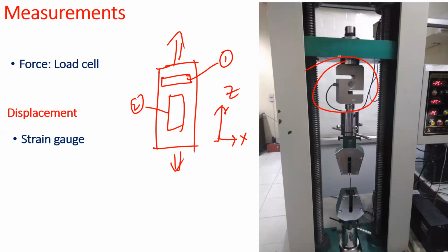So using strain gauges, one can measure the strains along the longitudinal as well as the transverse directions. However, the flip side to strain gauge measurements is that one has to always stick the strain gauge to the sample. It is a contact based measurement. It is still in use just because it is reliable.